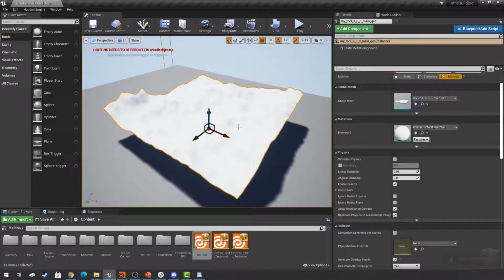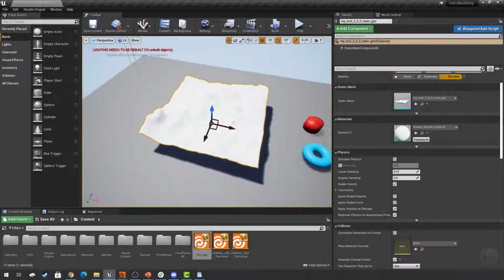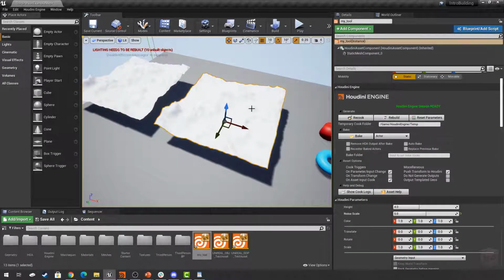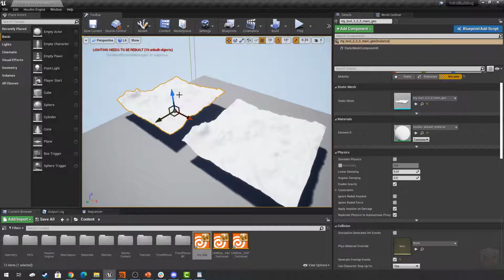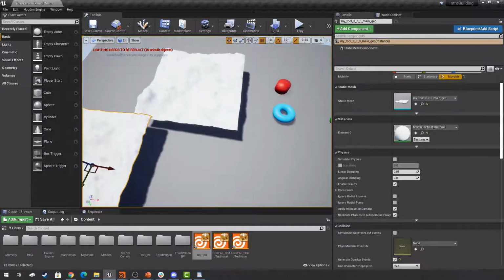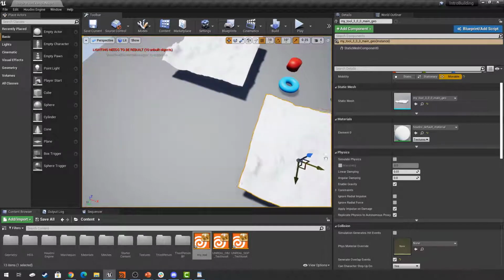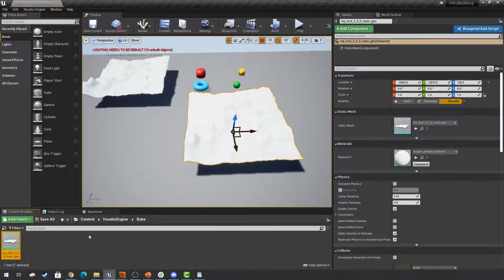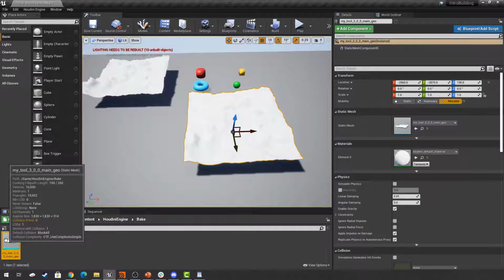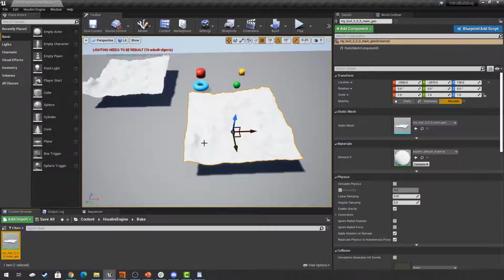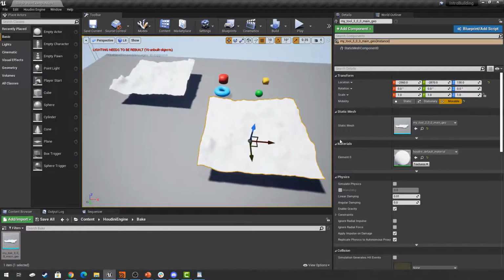And now what has happened is that we have made a duplicate of the mesh from our digital asset located in the same location. So here's our asset and here's our copy. And we can have this asset and we can move it somewhere in our scene. It's now a permanent addition to my files. And if we then go ahead and look on the file in its file location in Unreal, we will find it in the Houdini engine bake folder. So we can of course grab it from here, copy it somewhere else. At this point, it's a mesh we can just play with, right?